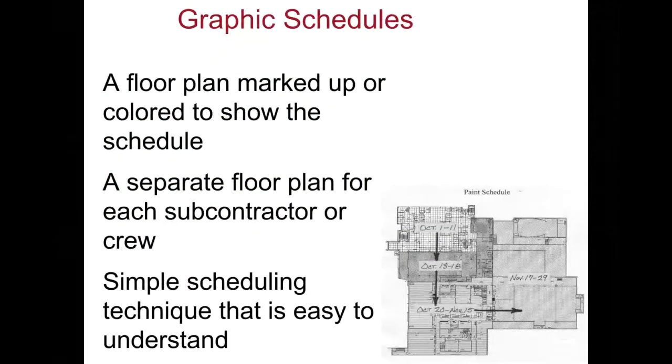So the use of different scheduling techniques depends on the nature of the project, how complex it is. Very often we see a lot of construction contractors just using very simple graphical schedules, using very simple tools such as a floor plan, marked up or colored to show the schedule. So for instance, if all the work is painting different rooms within a school, they could just use the floor plan and indicate that the work will be done here.